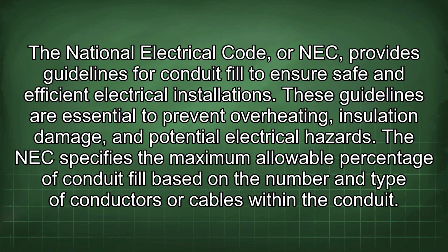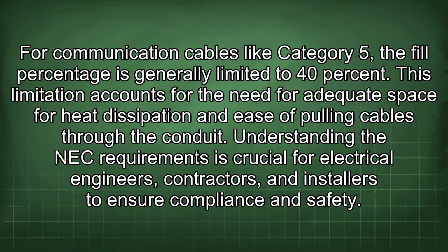The National Electrical Code, or NEC, provides guidelines for conduit fill to ensure safe and efficient electrical installations. These guidelines are essential to prevent overheating, insulation damage, and potential electrical hazards. The NEC specifies the maximum allowable percentage of conduit fill based on the number and type of conductors or cables within the conduit. For communication cables like Category 5, the fill percentage is generally limited to 40%. This limitation accounts for the need for adequate space for heat dissipation and ease of pulling cables through the conduit.